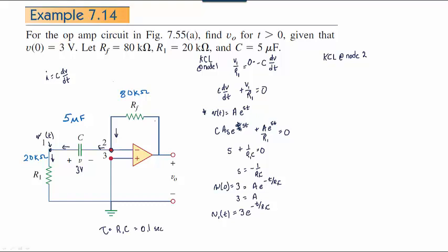So that's V out minus 0, and remember there's 0 volts right here by our rules of op-amp behavior for an ideal op-amp. So I'll have V out minus 0 over the feedback resistor right there will equal 0 minus, and again we will have C dV/dt. So V out over our feedback, let's do the algebra, equals minus C dV/dt.